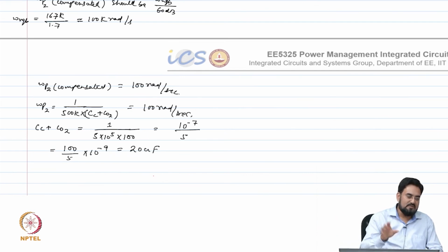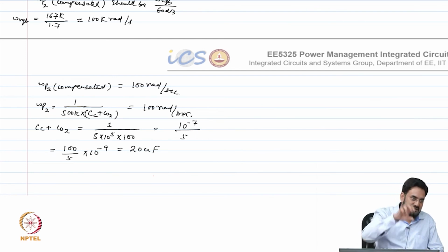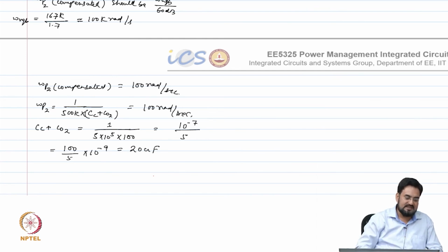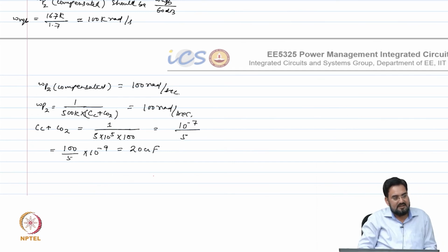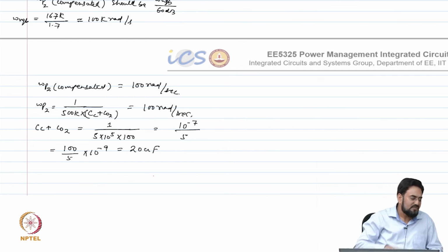Okay. So, in this particular case it is coming at the order of nanofarad. Let us say without Miller you might be getting 100 picofarad also, with Miller you might get 10 picofarad also. So, that is a difference, but even without Miller you can compensate it, because 100 picofarad is also possible to put on chip. The only thing is your area will be much larger, and that is why we go for Miller cap to reduce the area.